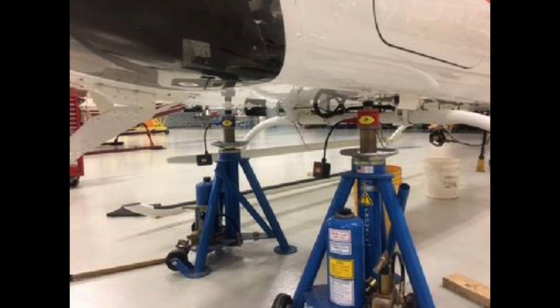Lateral level is not specified for all light aircraft, but provisions are normally made on helicopters for determining both longitudinal and lateral level. This may be done by built-in leveling indicators, or by a plumb bob that shows the conditions of both longitudinal and lateral level. The actual adjustments to level the aircraft using load cells are made with the jacks. When weighing from the wheels, leveling is normally done by adjusting the air pressure in the nosewheel shock strut.